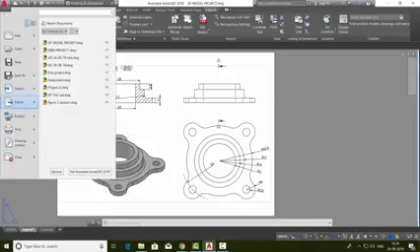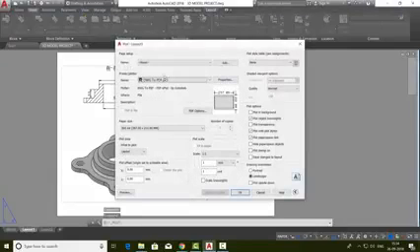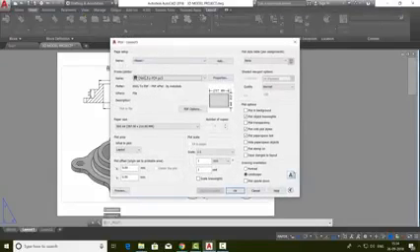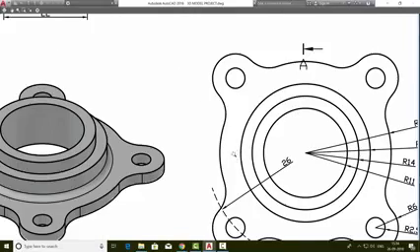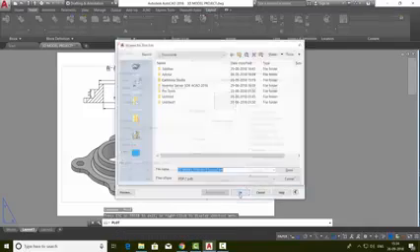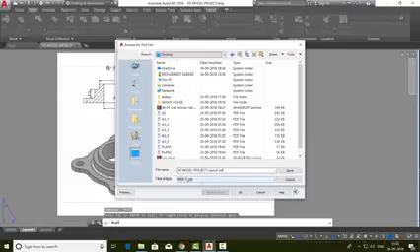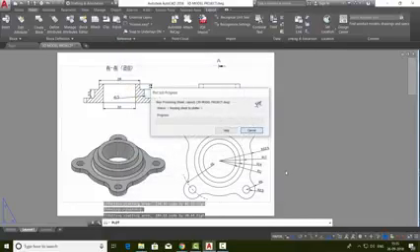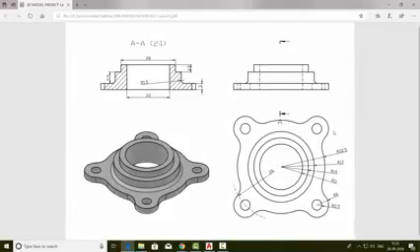So I'll go to application button, click on the print command and here everything is set. The layout will be plotted to the PDF file and you have selected the paper size, everything, you can just preview it. So this is how it will appear once you plot and now you can just give OK and your file will be named as the drawing file -layout.pdf. Now give OK, it's plotted.